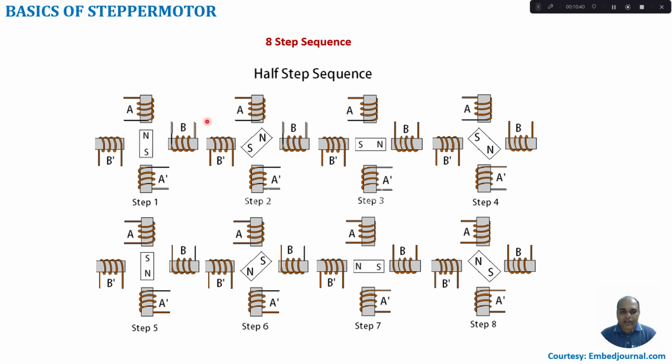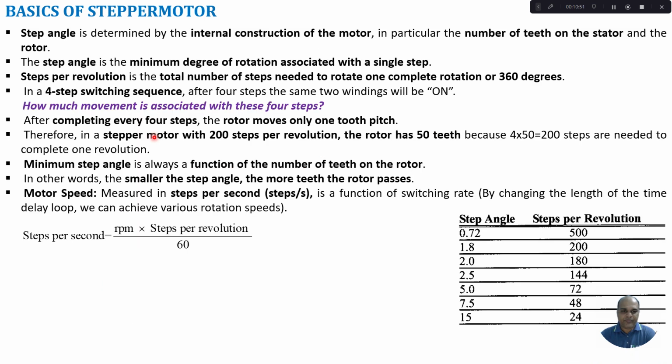Another method for getting more number of steps is by putting teeth onto the rotor and the stators. Thereby we can achieve more number of steps.